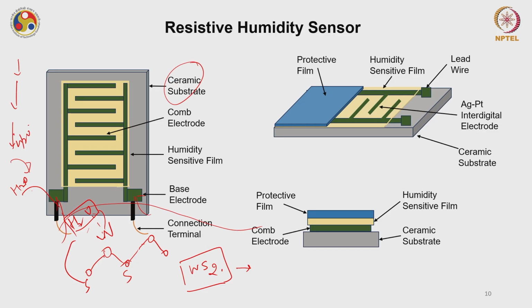So when you have this kind of structure, the last layers, particularly after the third layer, these water molecules form a kind of bulk layer. And you have some H+ ions, which can hop among this network. Therefore, apart from the electron conductivity, these resistive humidity sensors are sometimes also based on proton conductivity, because this H+ is nothing but a single proton. So because of this hopping of H+ in this bulk layer, sometimes you find a change in conductance or change in resistance.